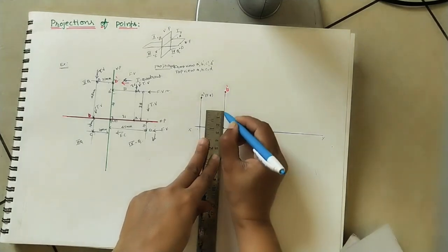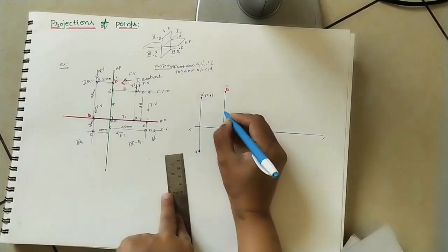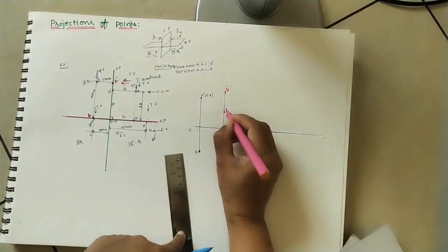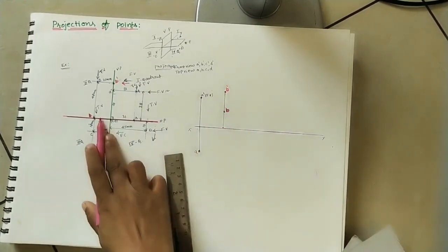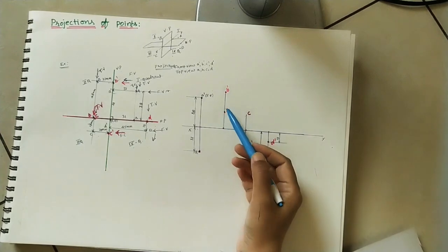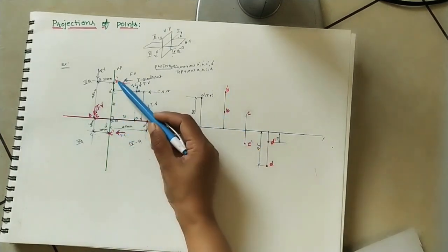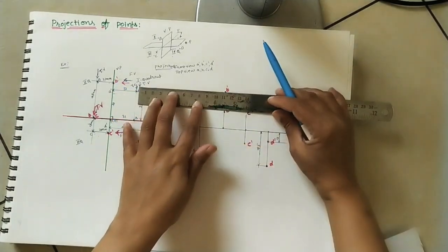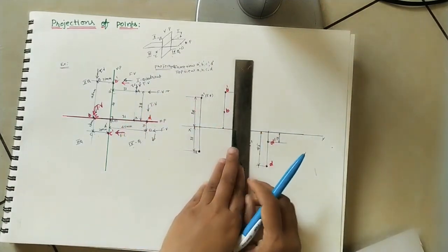Just make one point, don't draw one more line because both are coinciding and we already did the line. This point is the B point, make it dark. This is the front view and this is the top view of the B point in the second cube. For the dimension of B dash and B, where B dash will come, it is 48 mm. So here just do the extension line and mark this as 48.